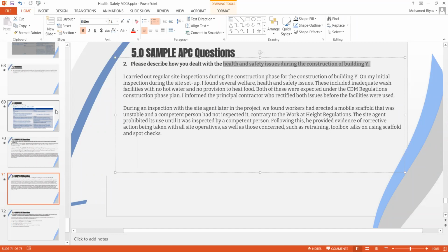So you'll start with the personal protective equipment, and the respective trades will have certain safety standards. You will always have a toolbox talk, and accordingly you'll start the activity. Then there is a method statement which needs to be followed. There is a checklist in place in the method statement. Accordingly, you'll make sure health and safety is in place, and there'll be a safety team at site monitoring the safety always, on site. So you'll connect all this as points to give a comprehensive answer.